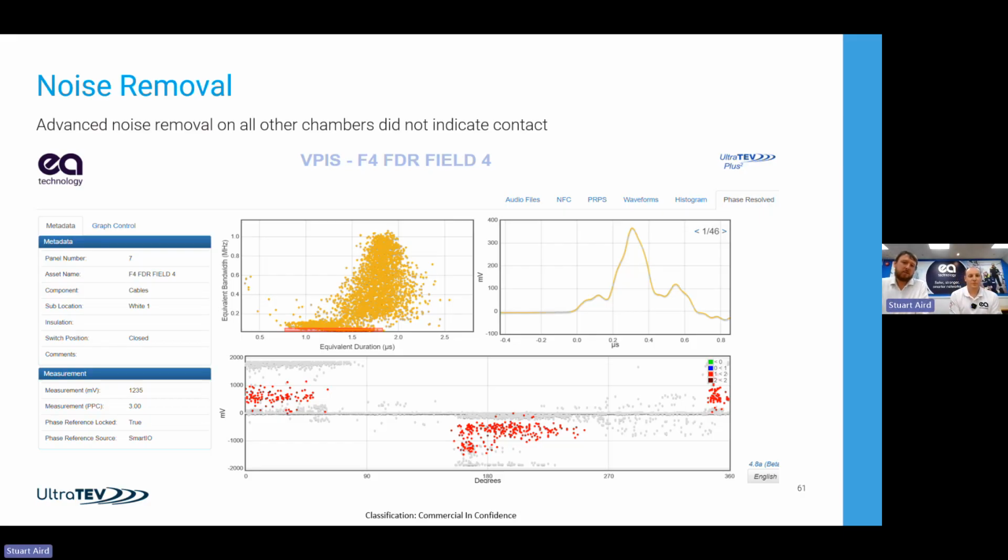So there is activity starting around the strain relief in the cables, where the stretch relief is. You've got some contamination on the boots themselves. There's some stuff on the bushings at the back. There's phase identification tape that's been left on. It's always one that causes a change in stress and, again, a breakdown of PD. All very early, all stuff that can be addressed, but plenty of bits of activity on there.